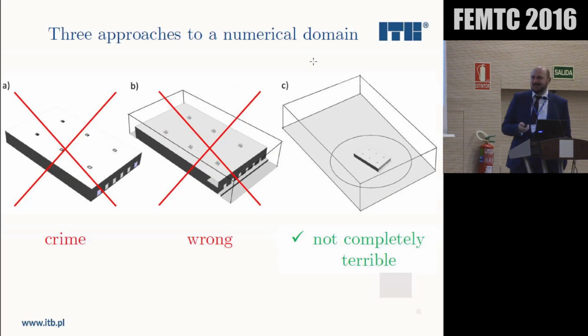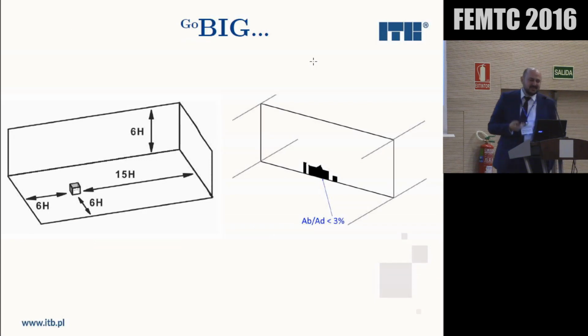The problem with wind engineering, and this is the first thing that hits you, is that you have to go big. I mean, it's enormously big models, and you have to get your mind around it. It's really big models. You have to go 5 heights of the biggest building you model in your simulation. You have to go 5 widths, and there's good reasons for that.